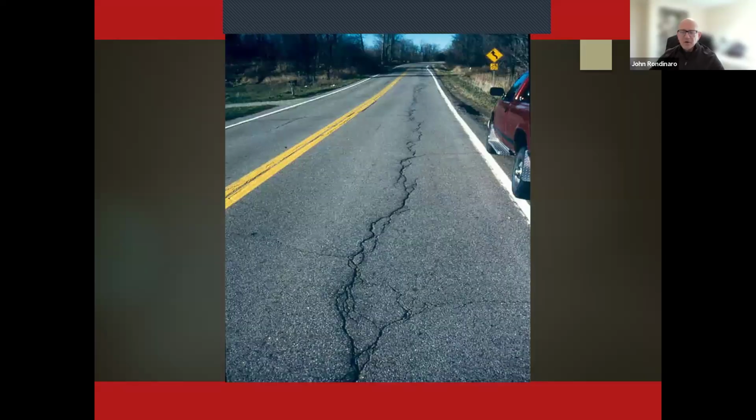This one is getting right to the edge of whether it's a good candidate, but if you came in and cut or routed that crack, you could still make crack sealing work, especially because you don't have any interconnected or secondary cracking. Once your pavement looks like this, with lots of secondary and interconnected cracking, crack sealing is not going to work for you. On top of that, it's right in the wheel path. So this is a load-related set of distresses, and crack sealing is really not going to help you when you let it get this far along.